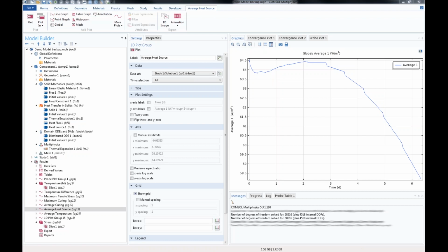What will differ is, for example, in geometric nonlinearity, for example, you could have a linearly elastic material that's going through large rotation or large deformation, then you might want to consider finite strain effect, right? If you're doing anything like buckling analysis, that's going to be important. So those kind of things are not available, but if you're just doing a stationary or time-dependent analysis on linear elastic materials, not just constitutive linearity, but geometrically linear as well, then there's no difference.